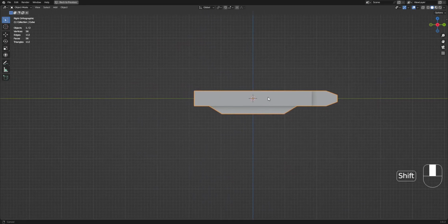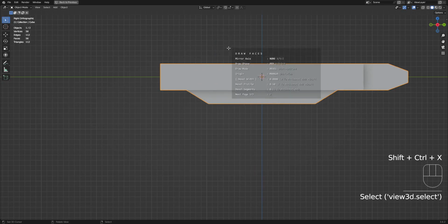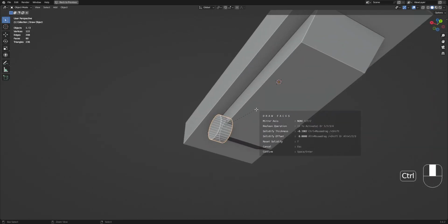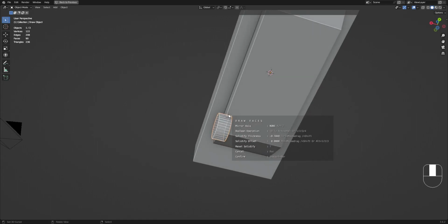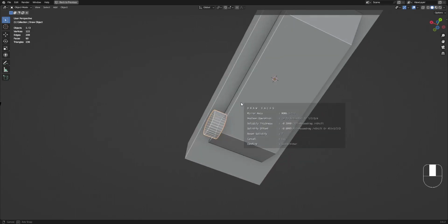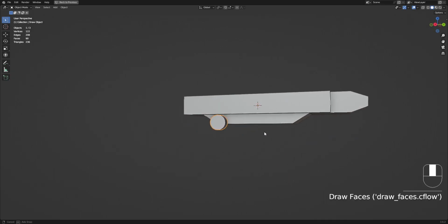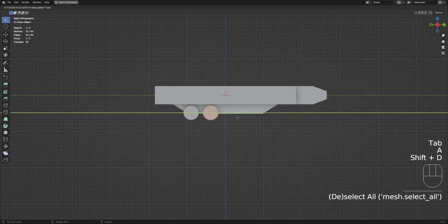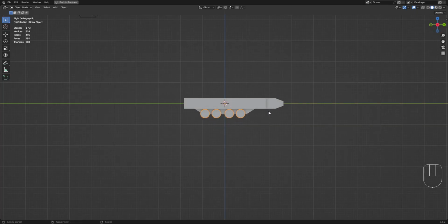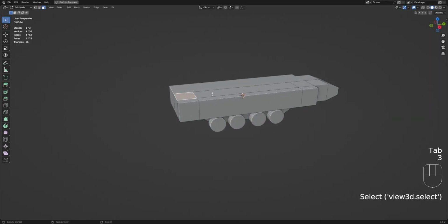in practical uses. Okay, I'm going to add the wheels and just draw them here, and set the start of the thickness on this face here. So I'm going to use Alt 1, 2, or 3. So Alt 1 and just okay. So see, it probably won't topple like that because